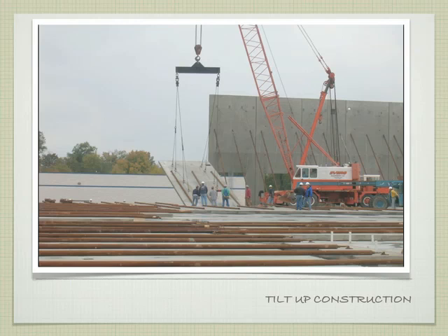In this particular example, they've attached these temporary braces to it. We also have our hooks that are attaching to the crane. The crane lifts this wall into position. It carefully guides it into position. You've got the people trying to guide it there. Then they attach these temporary braces while they grout the joints between them. They try to tie the whole building together.